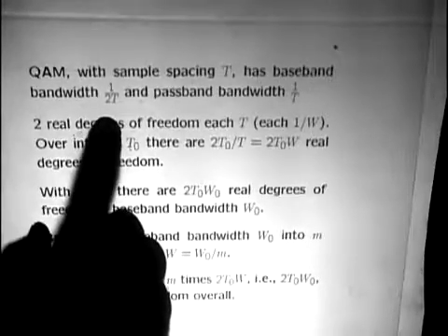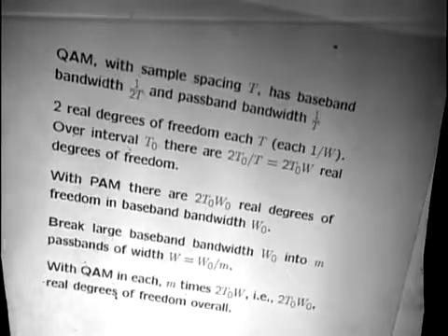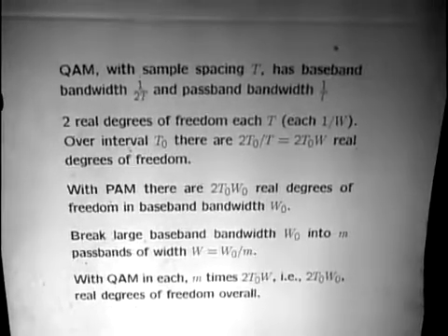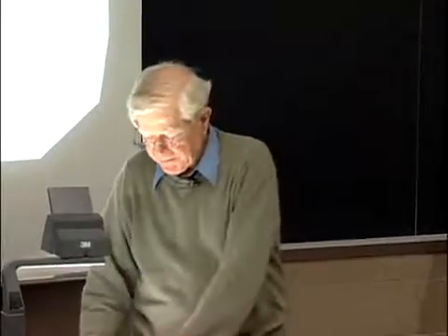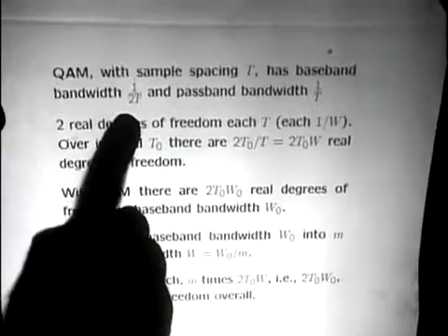Namely, that's what's called the Nyquist bandwidth. It's what you get if you use sinc functions, which strictly puts everything in this baseband and nothing outside of it. And we've seen that by using the Nyquist criterion and building sharp filters, we can make the actual bandwidth as close to this as we want to make it.